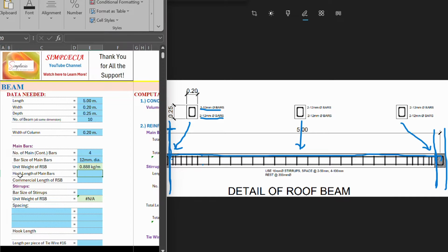To get that hook length, you need to look up your approved plans, kung ano yung ini-estimate mo na plan, and go to the general notes. The general notes is somewhere within the first 6 pages. Andun po siya, sa plano. Dapat yung approved, para yun talaga yung nakadesign, especially when you are on a contractor site. So for this example, I'll just use 0.15.